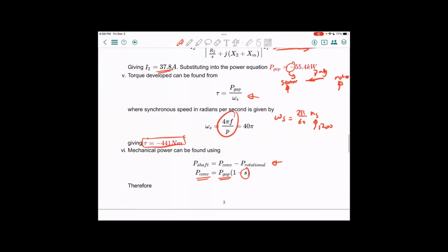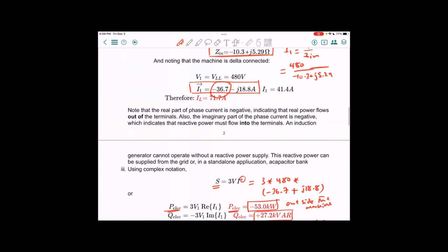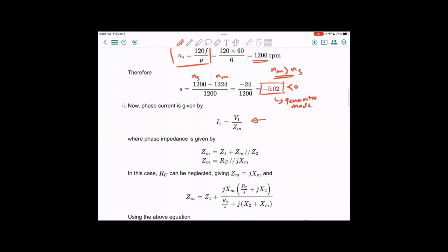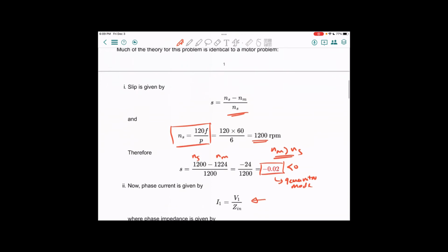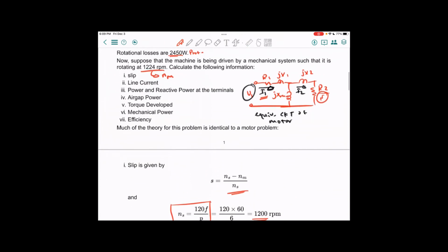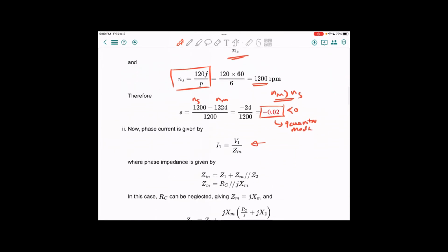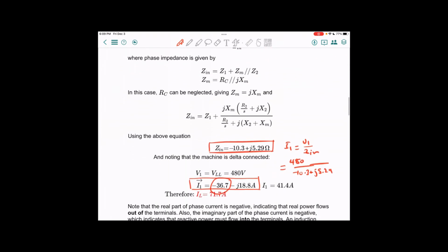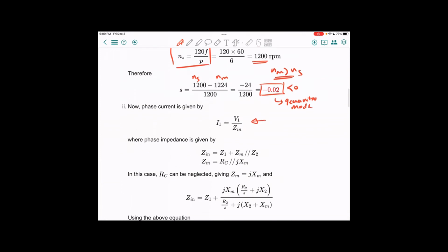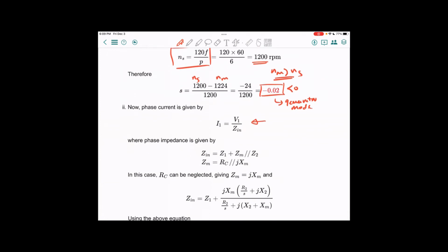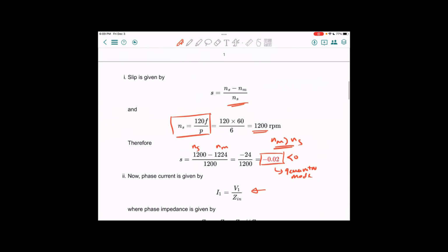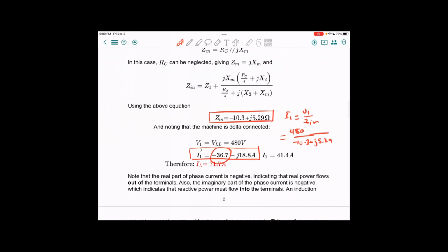So it's the same way we solved the same problems of the equivalent circuit before with three-phase induction motors, but we're doing this with the generator mode. Your slip will be negative, and you just go the same way doing everything. But now you understand what's happening here, why everything is just changing sign because of changing direction, and why your reactive power, your Q, is still positive here.